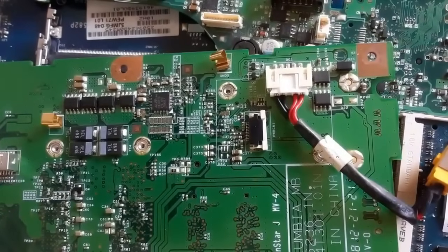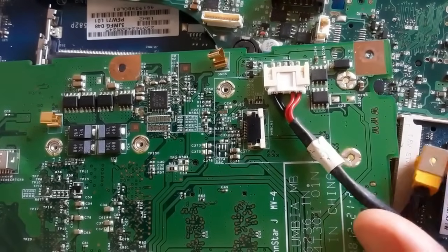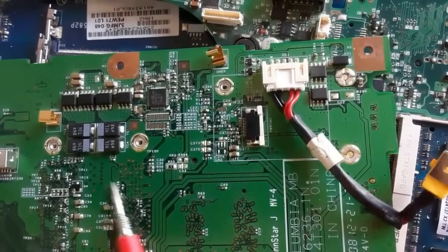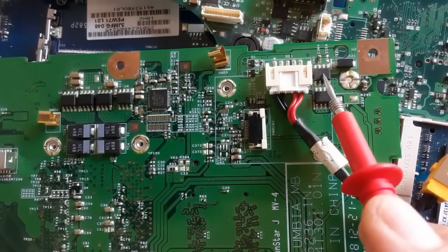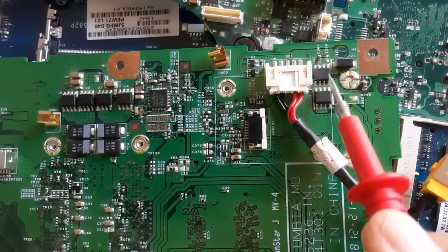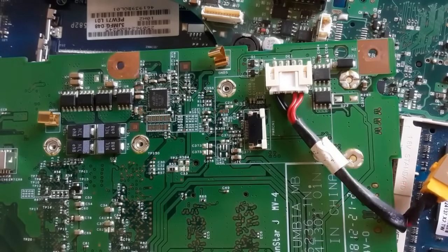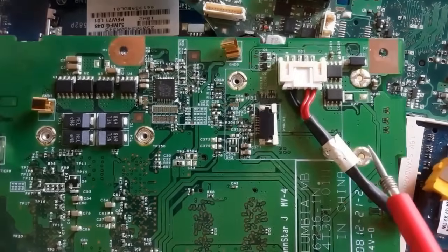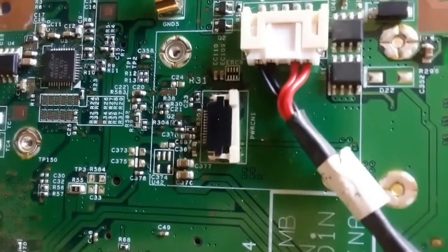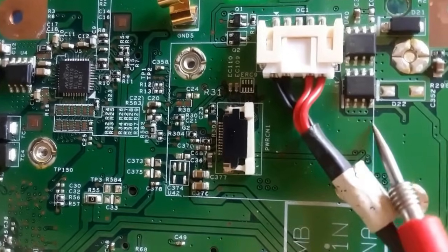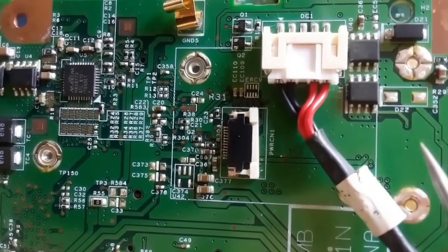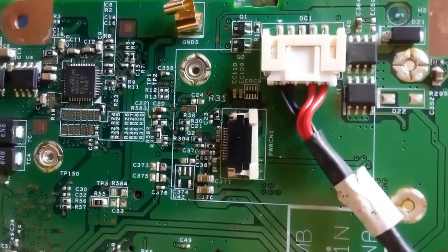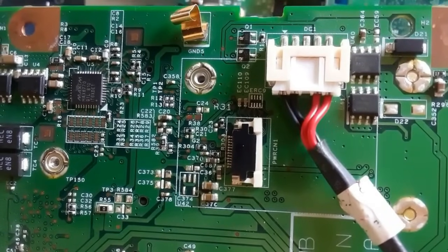As you can see also in this motherboard, this is the power jack connector. It is connected to the motherboard via a cable. Here we have the first switch or MOSFET and the second MOSFET. So these two MOSFETs let the 19 volts pass to other circuits in the motherboard. As you can see here, we have points. These points mean the 19 volts will go to 7 places in the motherboard, because we have 7 points here, meaning 7 places or 7 circuits.